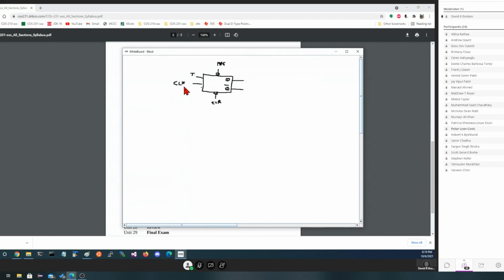And again, you have to look at the data sheet if it's got both signals marked. If, however, it has a little triangle right here, that means it's edge triggered. And the same rules apply. It's rising edge triggered unless there's a bubble, in which case it would be falling edge triggered. In that case, it might or might not have the overbar. So if I drew one that looked like this,